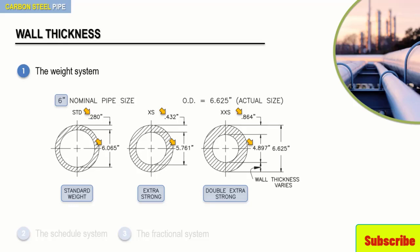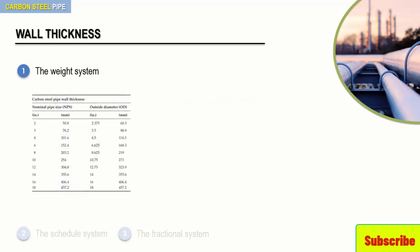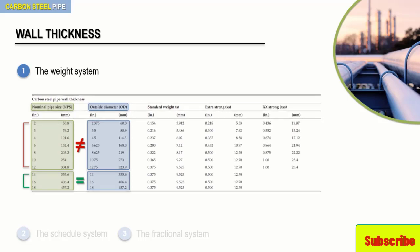Okay, now take a look at the following table. It represents carbon steel pipe wall thickness as a function of the nominal pipe size. As you can see here, for pipe 12-inch and smaller, the nominal size is not equal to the actual outside diameter. It is simply a convenient method to use when referring to a pipe. As a piping drafter or a piping engineer, you should be aware, however, that pipe 14 inches and larger is identified by its actual outside measurement. This extended version of the table shows typical pipe diameters and wall thicknesses using the weight system.